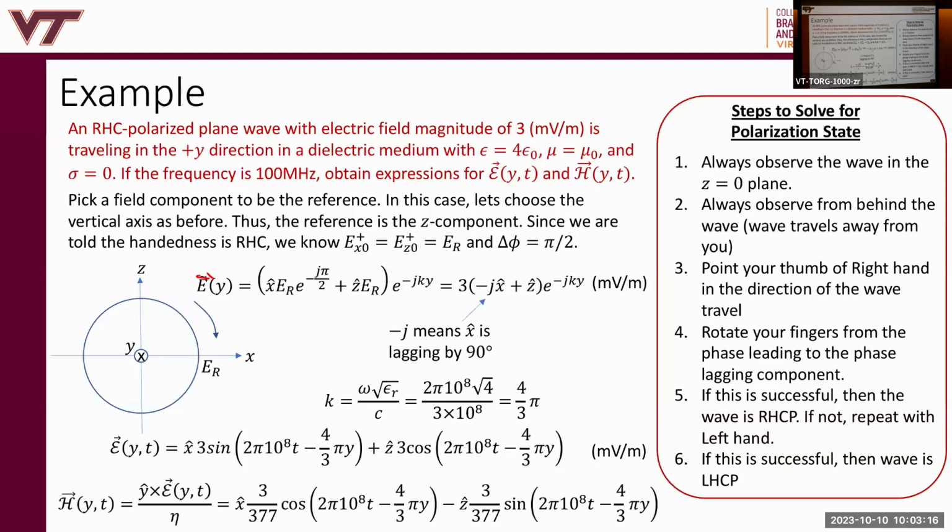Once you have the electric field, you can find the magnetic field. How do we find this magnetic field fast for a plane wave? You guys remember? We don't need to use Faraday's law for plane waves. We use our right-hand rule. E cross H is always the direction of propagation. So E cross H is K. We know E and K already, so we can find H, the direction. And then we divide by the wave impedance, right? Not eta_c because it's a lossless medium, it's eta. You remember that, right? Okay, good.